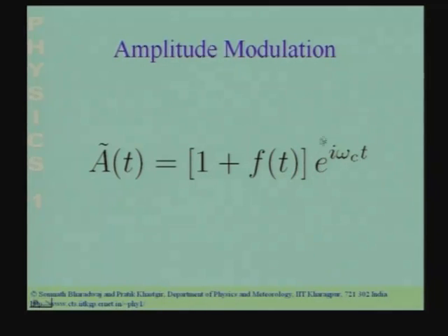So, the signal generator produces a signal at the carrier frequency, the amplitude of this is then modulated with the signal that we wish to transmit, and this is what is transmitted. At the receiver end, again there are devices through which only the changes in the amplitude are recovered, and from this you can get back the voice which you wish to transmit.